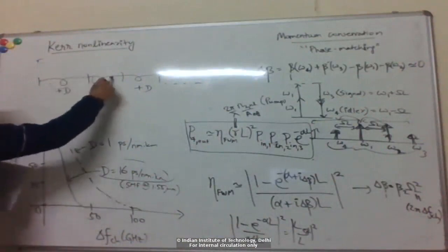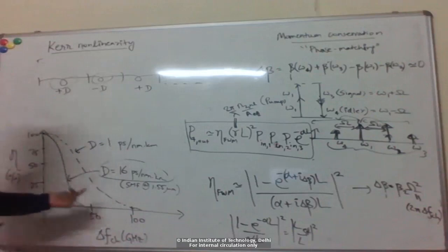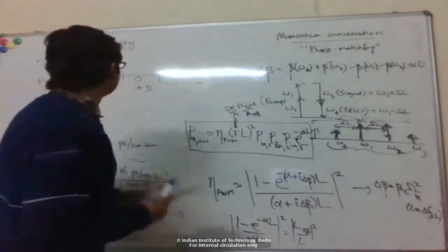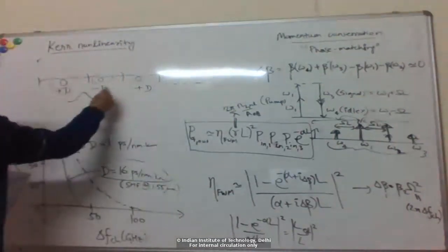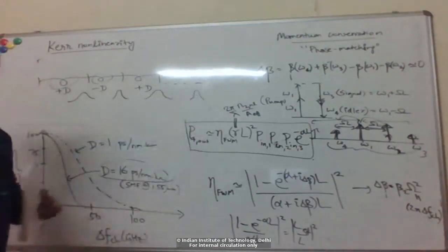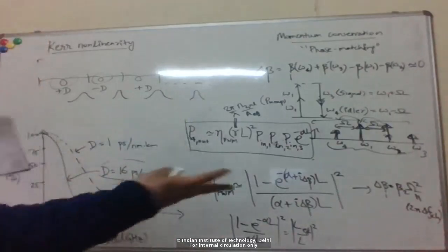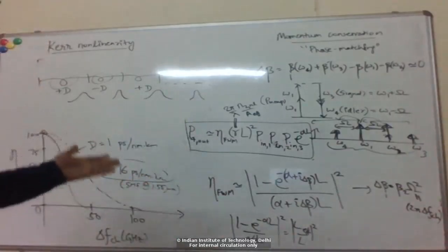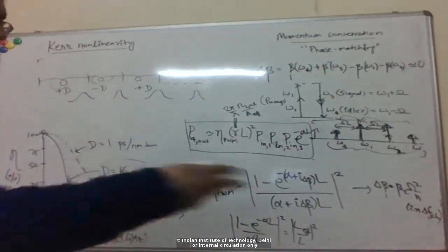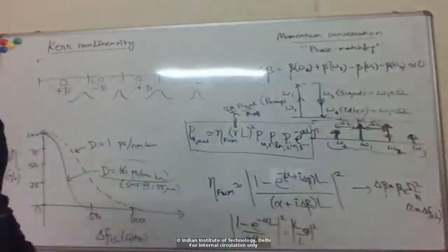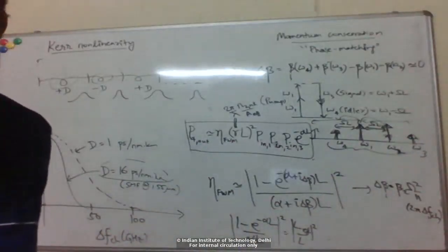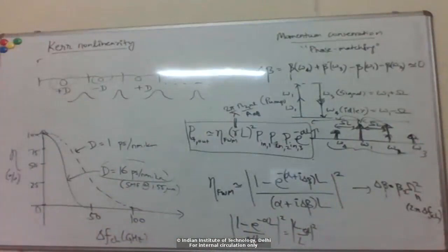Yeah, so in each of these sections, if the D is large, you've eliminated four-wave mixing, but because of this inversion, the broadening which has happened here will be compensated by the negative dispersion here. So overall, you also compensate for the linear dispersive broadening along with four-wave mixing, if you have these locally large values of dispersion, but average over the link near zero dispersion.